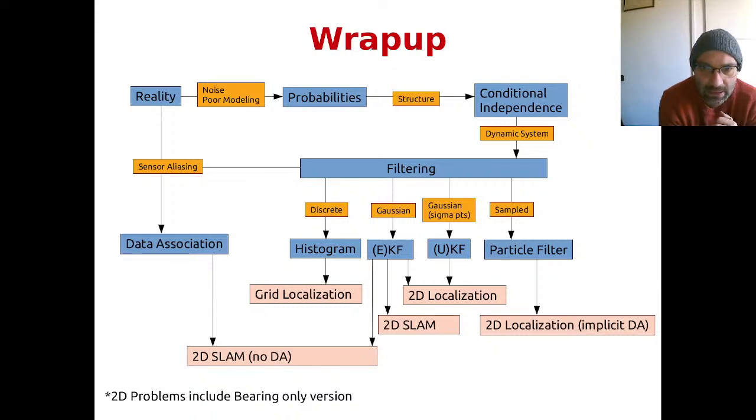and we have seen that all possible filters that we have presented in the course basically follow the very same derivation. They come from the very same machinery, which was the Bayesian filter derivation that used the chain rule and conditioning for the state, chain rule and marginalization for the state transition, and chain rule and conditioning for the update. So we have defined this demonstration, so to say, of the filter, and then we started deriving different algorithms which were implementing this very same constructive proof, and the different filters basically differ from each other in the assumptions that they make on the underlying probability distribution.